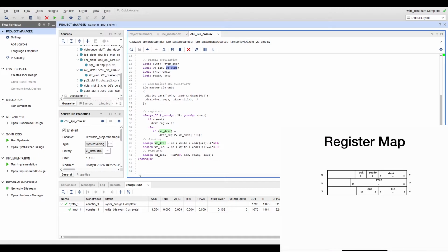So let's take a look at it. If you look at the register map, we only have 1 read register, so technically we don't need to do any multiplexing, but we have a couple of write registers, so we need to do some decoding. So I'll jump directly into the read, and in the read you can see that all I'm doing is just packing them. There's no need to use the address at all because I'm not multiplexing. Of course, the decoding happens in here.